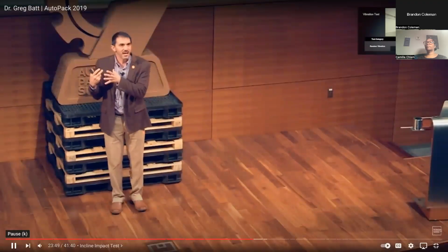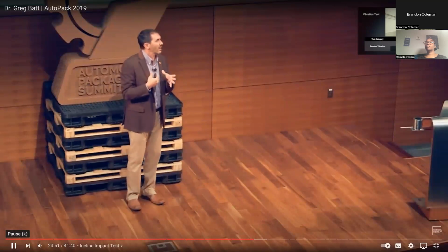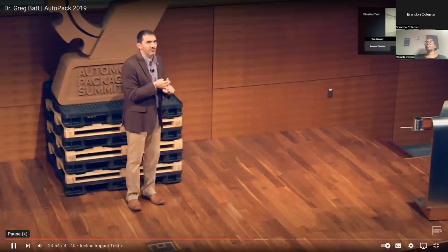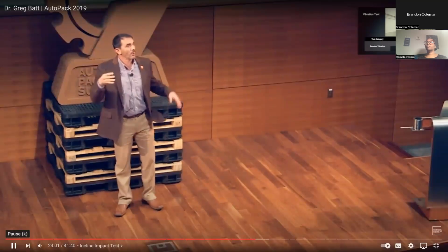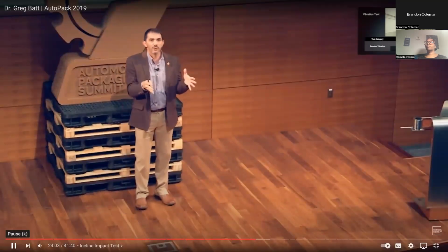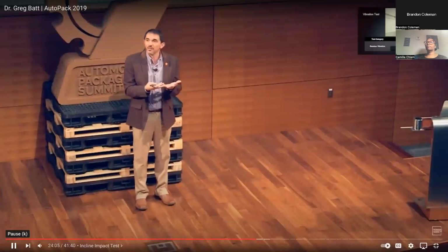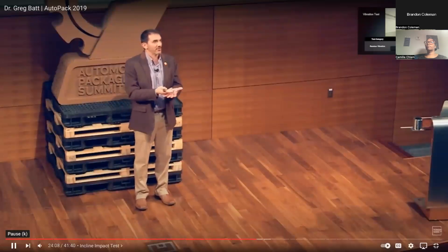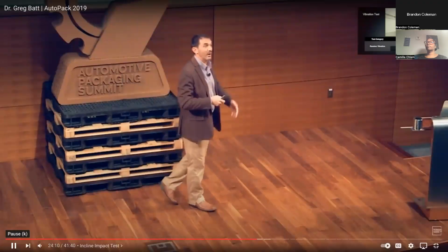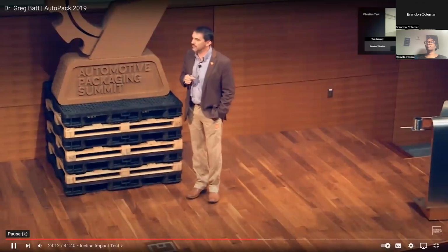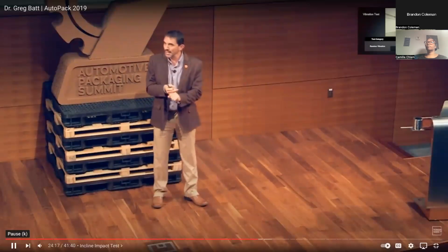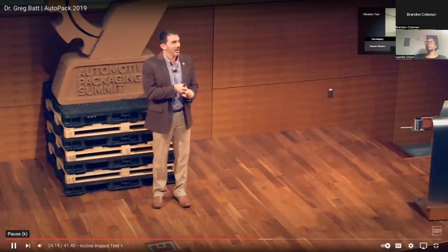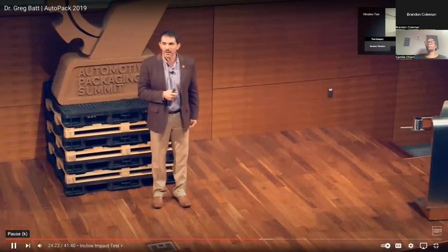When we do a vibration test, we are not simulating that truck going over potholes or railroad tracks or the speed bump or catching the curb as they go around the corner. Those discrete events get filtered out. What we're capturing is the over-the-road response of the vehicle to that rough road surface, which we get exposed to for hours. So we're not seeing the discrete events, but there are profiles that exist for trucks, for planes, that we can use and play on these vibration systems.